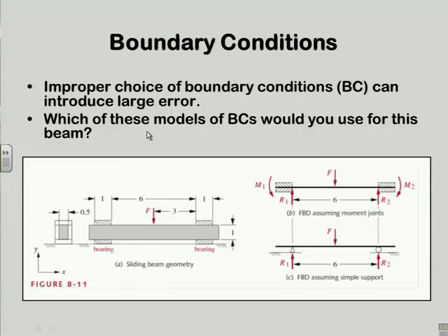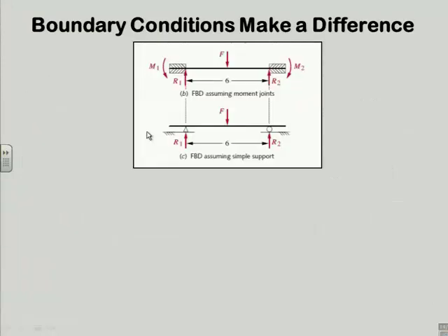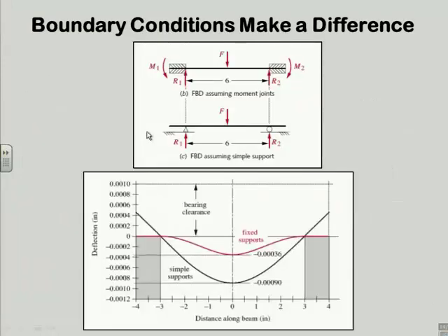So there's no such thing in the real world as a true fixed joint, because that assumes that the building that it's on and the ground don't move at all, right? Well, for most applications, that's a safe assumption, because I got 100 pounds on the beam, the building weighs 80,000 tons, and there's Mother Earth under me. So I'm not going to fret over that sort of thing. But nevertheless, the FEA is going to think everything is perfect. So let's look at what kinds of results we get.